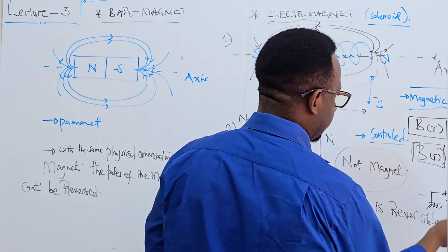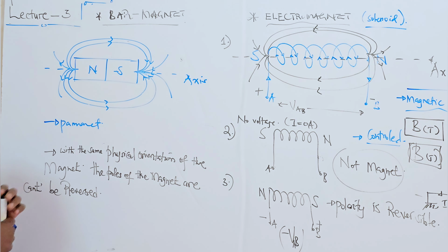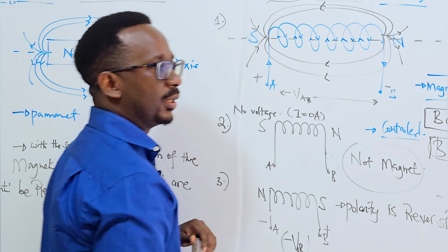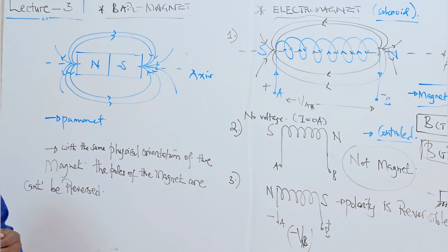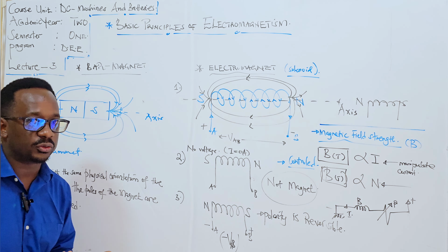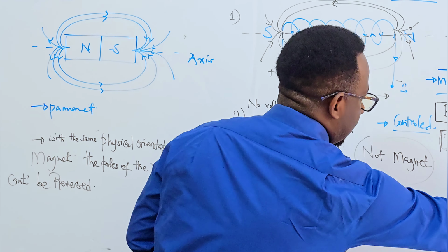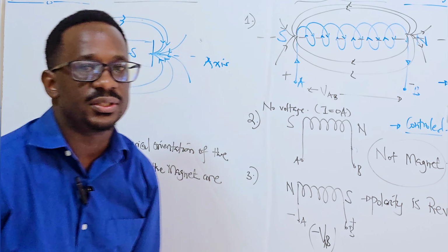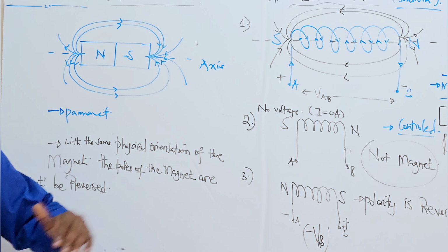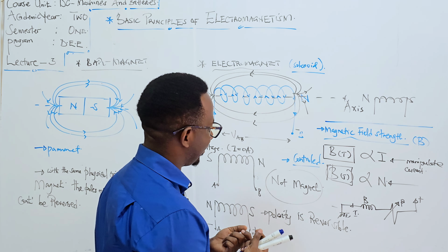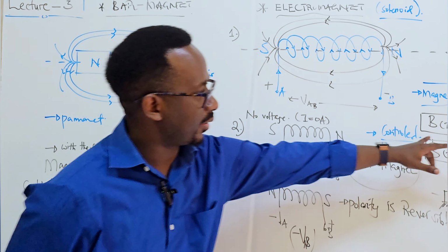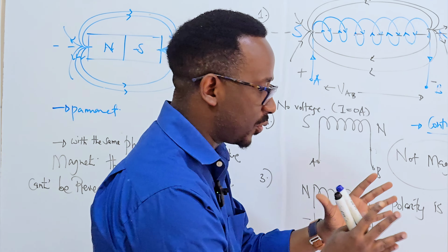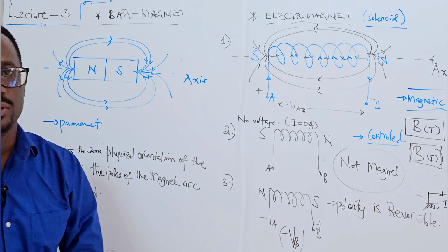So we've seen that, I'm going through conclusions, that with clever circuitry, now you remember why we had the KVL and KCL principles stated in the first lecture. Now we're having loads in series that have a common supply voltage. That means we're going to have individual voltage drops across the coil and the resistive load, or the rheostat, or the variable resistor, or a potentiometer if the motor is that small. By just changing the current, we can change the field strength. That means we have a magnet whose parameters can easily be controlled by changing the electrical properties of that coil.